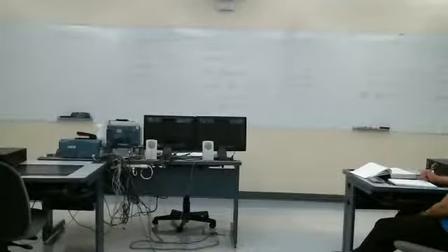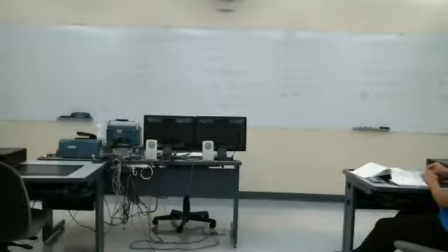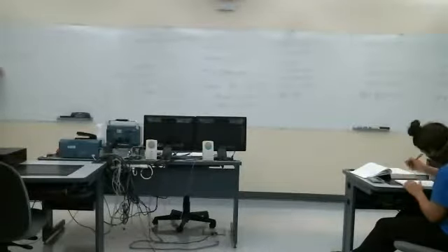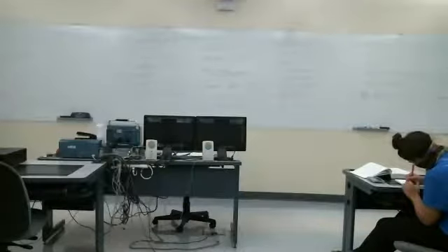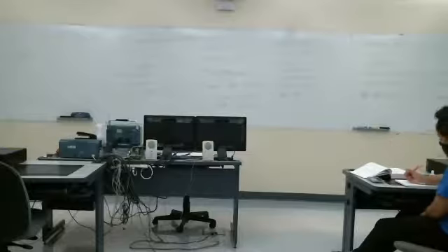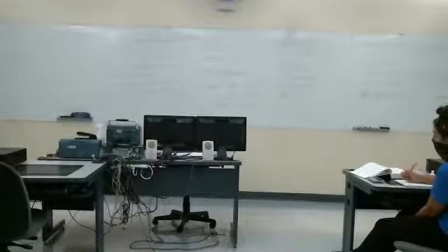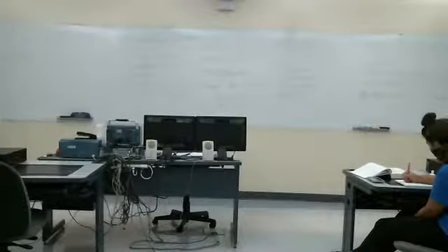Okay, so I can theoretically find the impulse response of that RC circuit we started with. Find h of t for the RC circuit. y step of t, we had for that, 1 minus e to the minus t over tau, u of t.